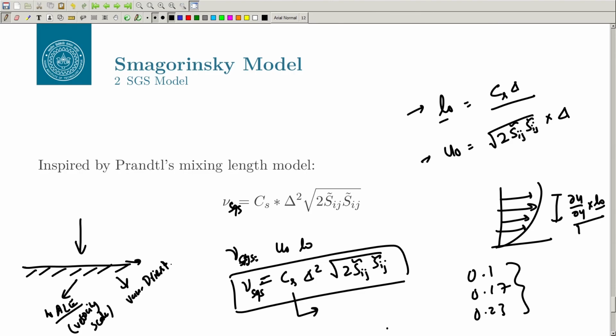And then we have some kinetic energy based model, TKE based model. What they do is that they change the equation itself when it approaches the wall. So, this is a very important aspect, and that is why you have many models when it is a wall mounted flow.